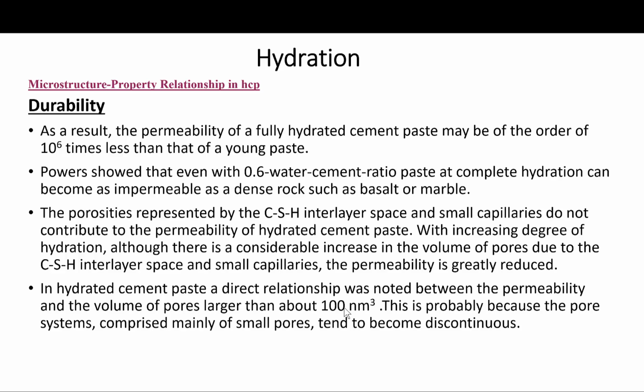Powers showed that with complete hydration, a 0.6 water cement ratio paste can become as impermeable as a dense rock such as basalt or marble. So complete hydration is key, and that means in practical terms curing and water loss prevention after pouring the concrete.